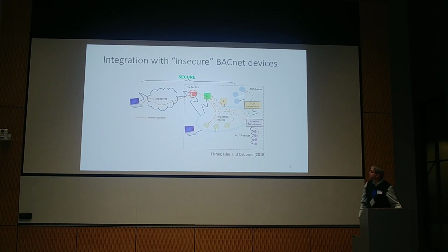So in the scenario I mentioned before, I could still find that thermostat that Siemens installed, and if it's an MSTP thermostat, I could plug in my MSTP device and I'd have access to the entire network. So this is not fixing the security issues around non-SC devices and components of the system. It's an excellent question.